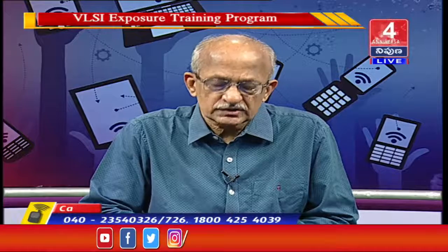To understand scaling, we must look at the MOS transistor and its fabrication. I will go through a simple example of how an inverter can be fabricated. Of course, this is an isolated picture of an inverter. Don't think that an inverter is fabricated as a separate part. No, it is only a part of the ASIC, which we will see starting from a substrate, how it will go through.